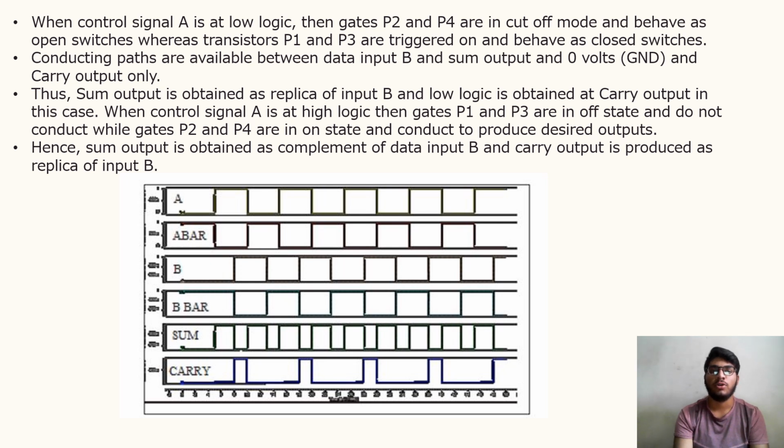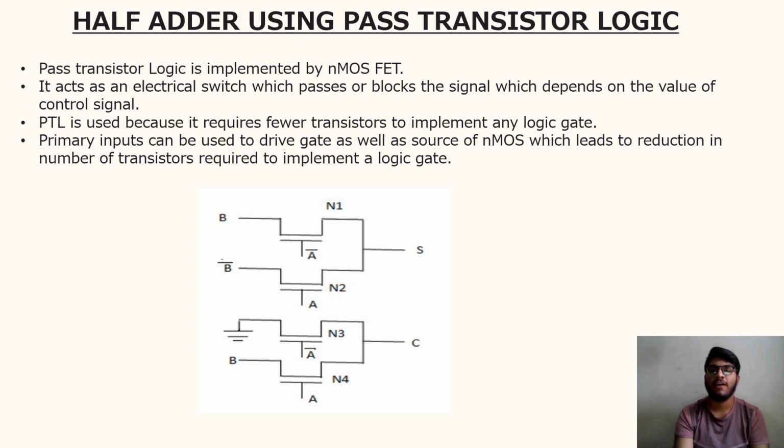Hence, the sum output is obtained as the complement of data input B and the carry output is produced as a replica of input B, and the simulation is also represented in the waveform, which is given. The next is the half adder using pass transistor logic.